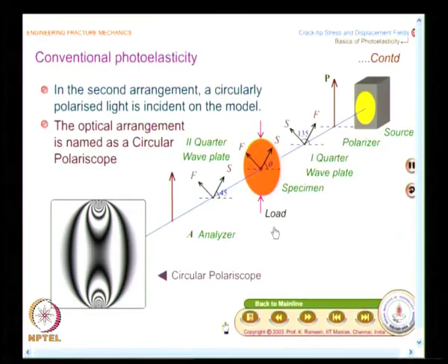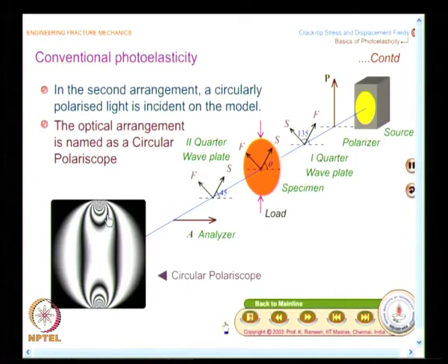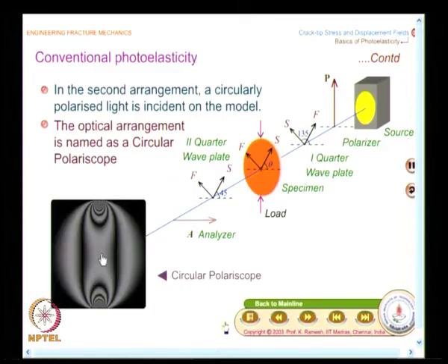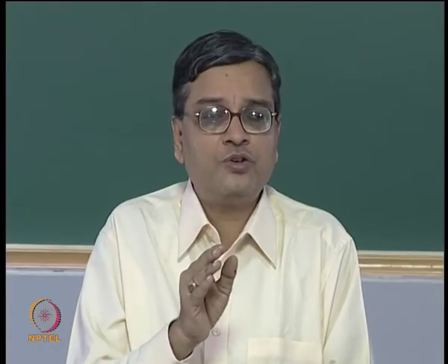What you have to notice is that in the experimental fringes, the thickness varies. If you see here, the thickness is very broad here. When you say a contour, you will have only a line. Where you are plotting the fringe order, you will have to give a small variation and analytically plot that, and you will automatically get a thickness variation. There are papers written on that, you could look at the references. So, if you know sigma x, sigma y and tau xy, it is possible to plot.